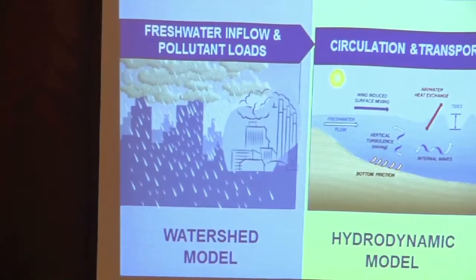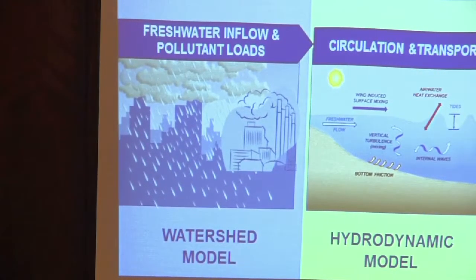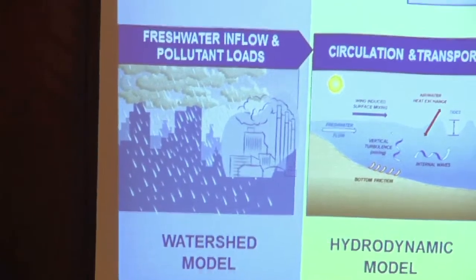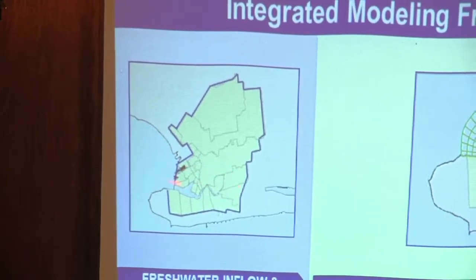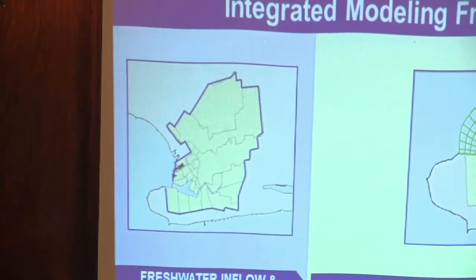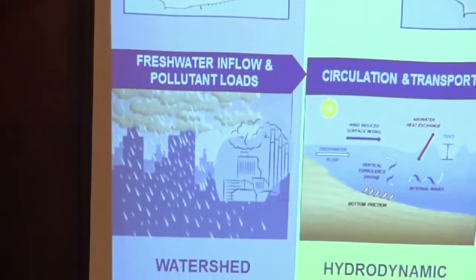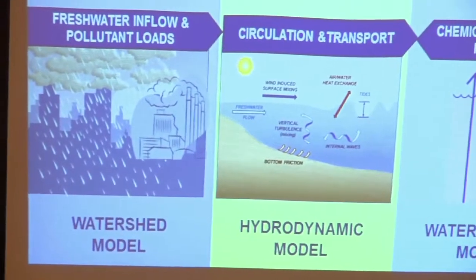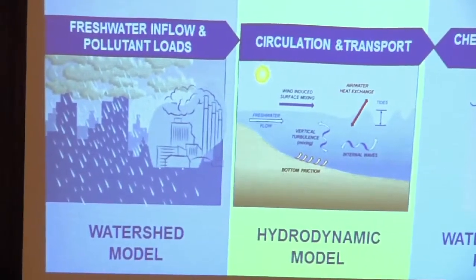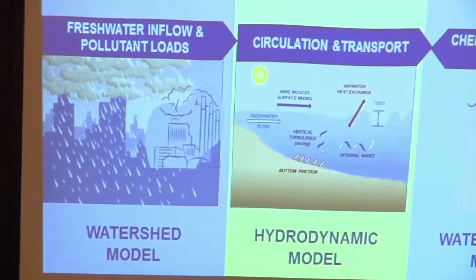And they look into how the runoff gets generated after accounting for all the losses that happen to the rainfall and how that gets translated into the runoff. And then the second step is, that results in the combined sewer overflows or storm discharges from the watershed model. Then we put them as the inputs to the water quality model.